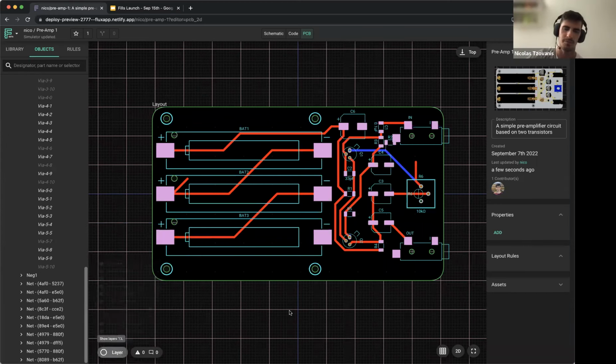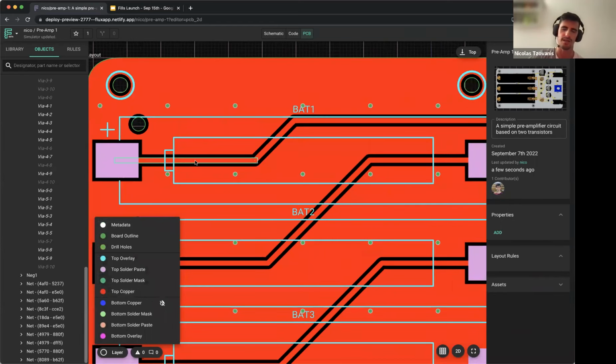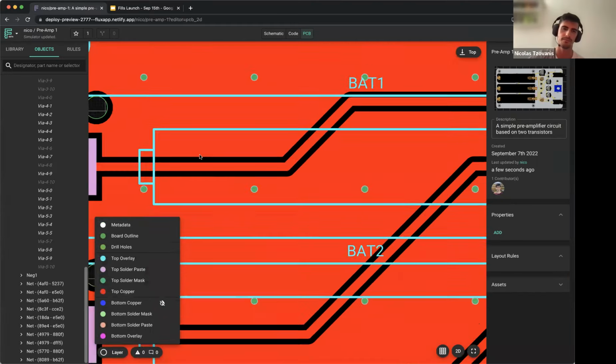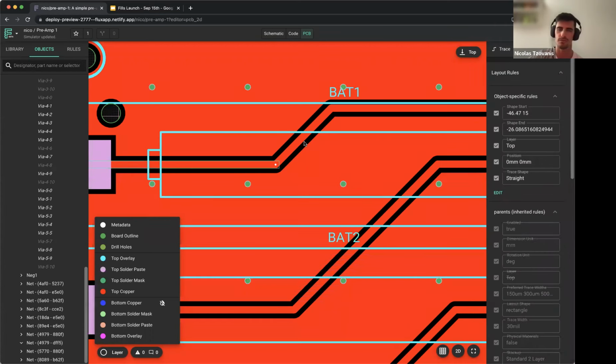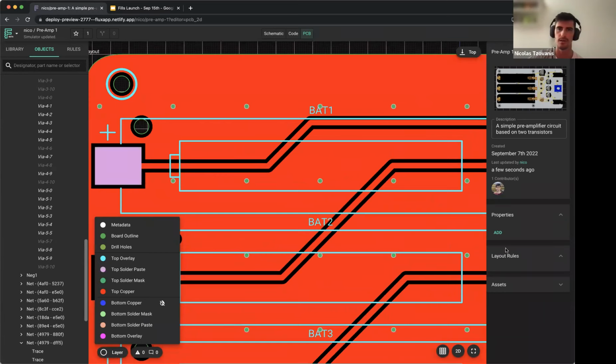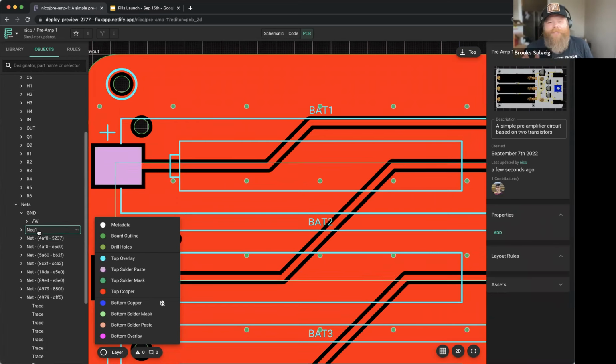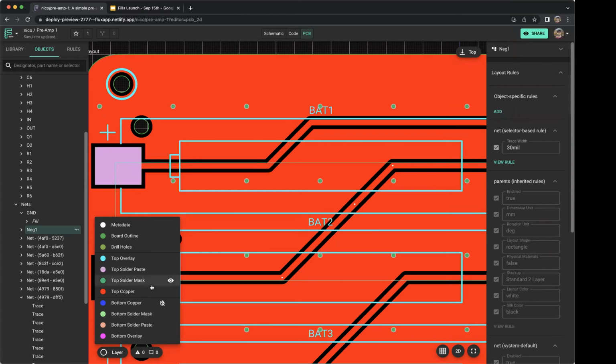Sorry, you mean spacing around? There's something that I forgot to mention. You have the spacing from the trace to the ground fill. You can define different spaces for each trace, net, pad, or whatever, and you can do so with rules. Andrew, which spacing are we talking about? Are we talking about spacing between tracks and ground fill, or spacing between vias? It's the via spacing, the ground fill.